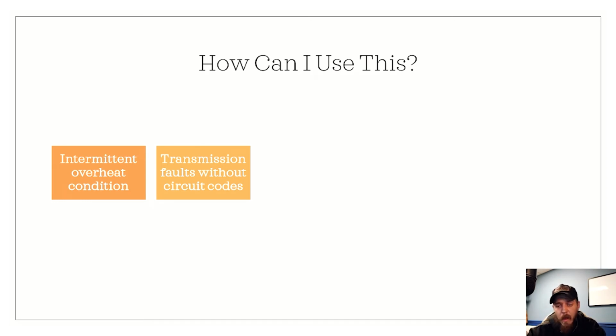It was bad. All that, along with the fact that pressures were good in scan data, we didn't see any mismatches, anything else, led me to believe a low-speed fluid flow condition from the transmission pump. I was able to come to that conclusion through a combination of service info, readable data, actual pressure testing, and understanding how hydraulic systems work. We make a lot of hydraulic calls, a lot of transmission calls, where we can only see so much.